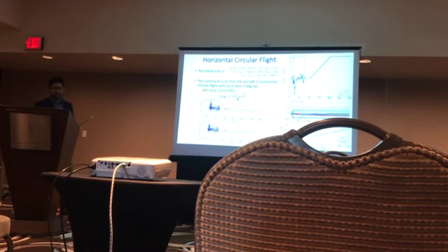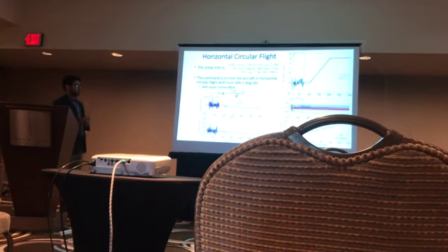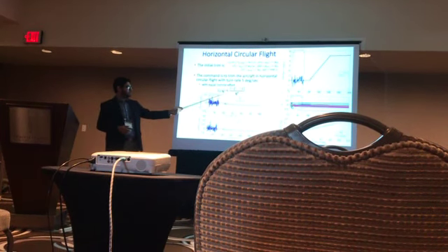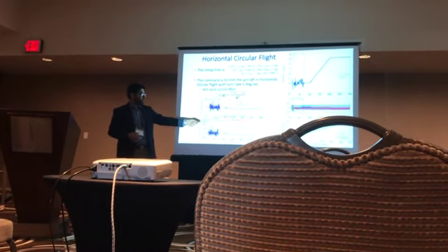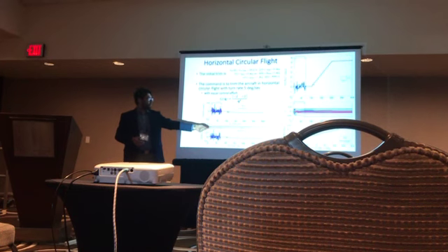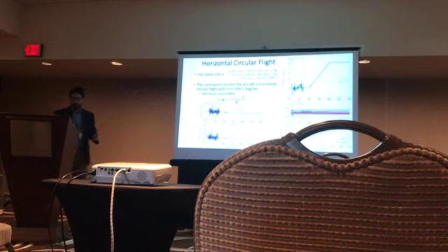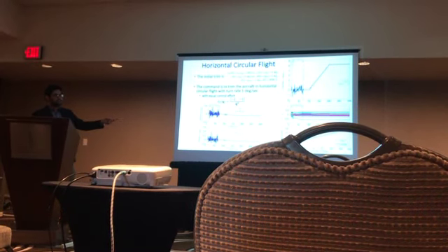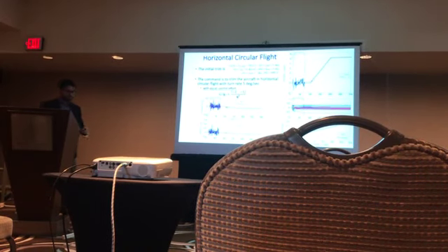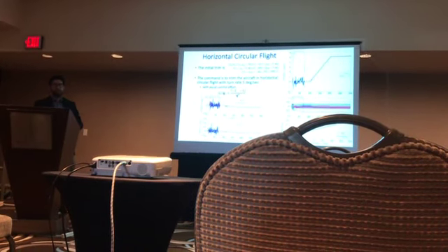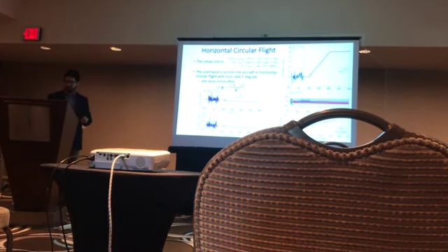Now, if you wanted to use slightly different ratio of the aileron and rudders, all we have to do is set up these numbers slightly differently, and we see we get a similar response, not the same response, but with a slightly different combination of the aileron and rudder based on our choice of the filter coefficients. So this is basically using, I don't want to say a flaw, but a structure in the RCAC computation.